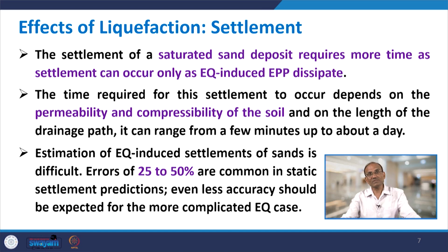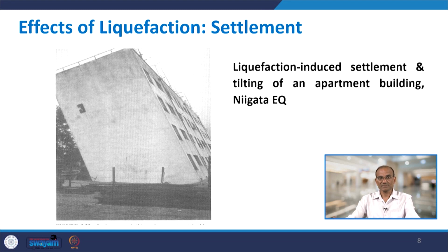The time required for this settlement in a saturated deposit to occur will depend on the permeability and compressibility of the soil deposit and on the length of the drainage path, and can range from a few minutes to about a day. Estimation of earthquake induced settlement of sand is difficult, and there could be errors of 25 to 50% for static settlement predictions. Even less accuracy can be expected for the dynamic case.